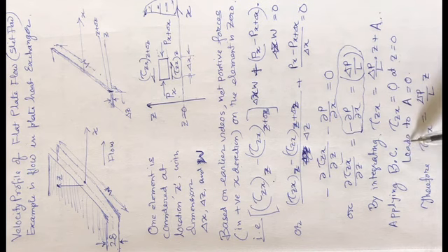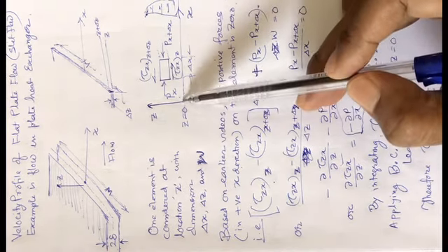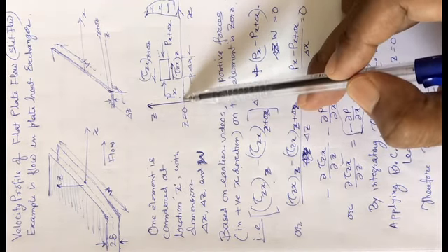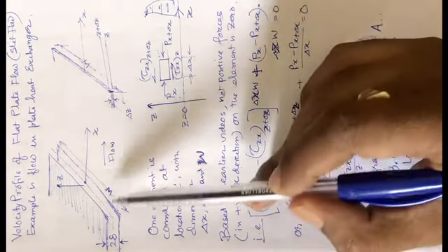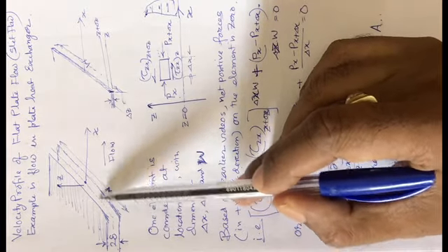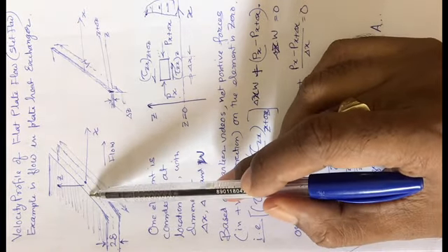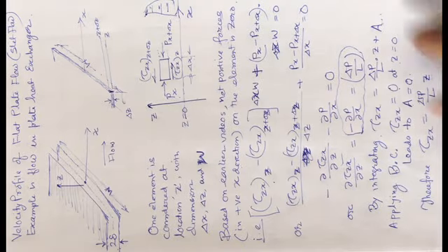So this leads to A is equal to 0. It means tau zx is equal to delta p by L multiplied by z. Okay, z means position; you will have to measure that position with respect to the midpoint of this particular gap. So there is a central plane, and from the central plane we will be moving upward, that is the position z.